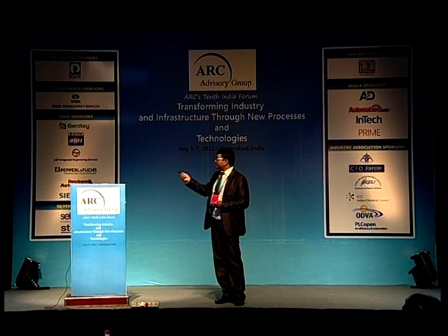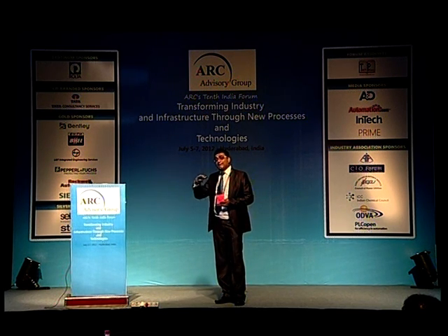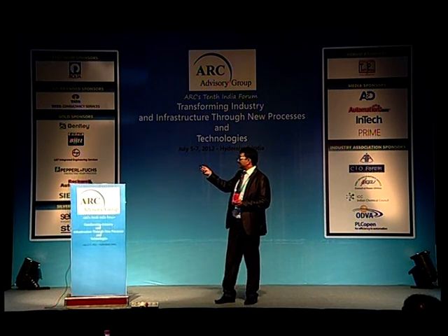So you can see at the top, in the economizer, it is also showing the color system. Red means that it is telling you to do soot blowing. If you see, second from the top is the economizer, where it is showing all the blowers in red color. So it gives level-wise soot blowing advice. Here it is telling you to soot blow.